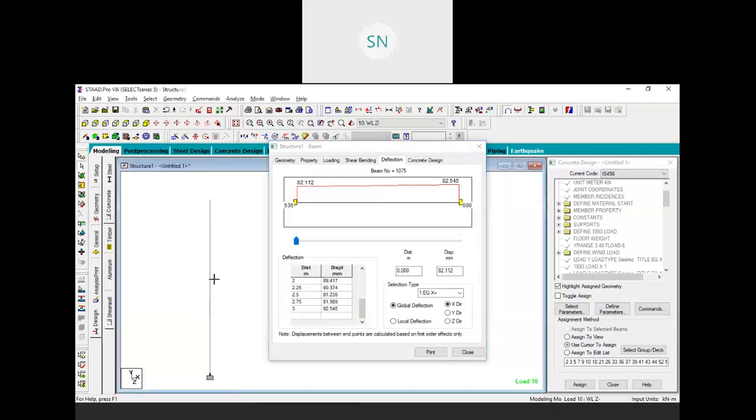Okay, so here we have 1 2 3 4 5 6 7 8. So top 8 floors are fine, but from the bottom we do not have that reinforcement detail. So that warning is due to this thing, because this column is going to fail in my reinforcement detail. So we need to increase the size of this column, right? That is our design and optimization problem.